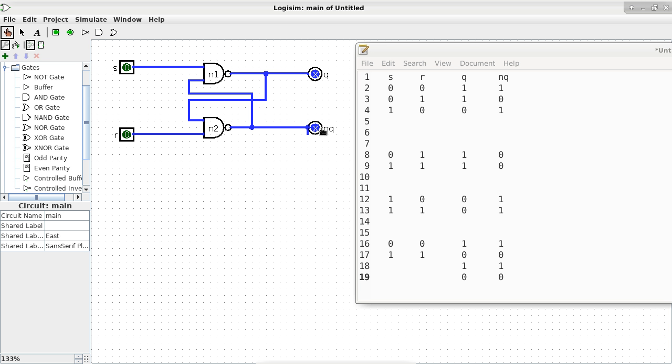Okay, let me test you one more time. Why is this device the basis of memory devices? What makes it qualify as a quote-unquote memory device? What does it remember? Well, because when you change one of the inputs, it will still have the same output. Yes. Particularly when both inputs are ones, it remembers what it was before that state. Okay? Are we good so far?